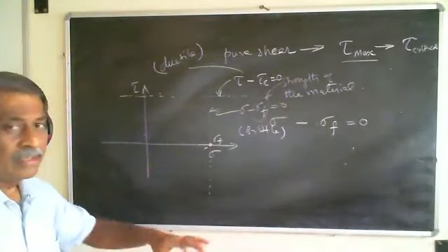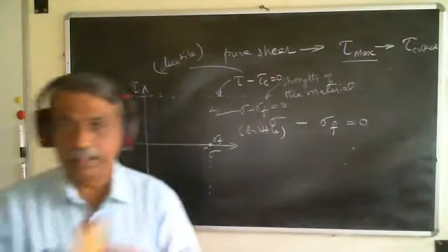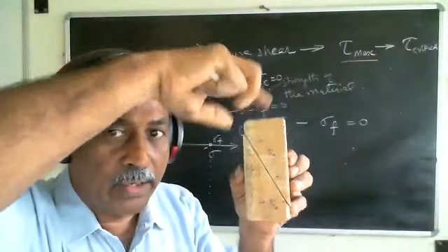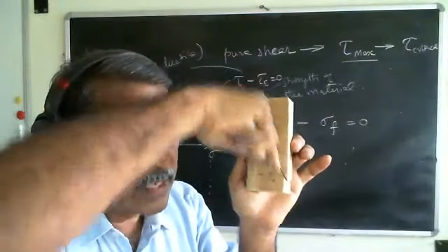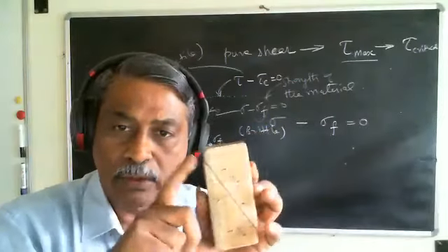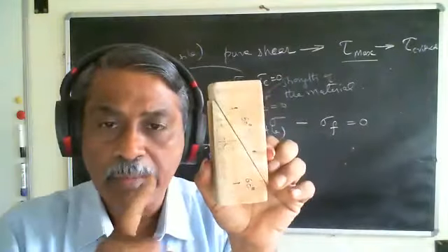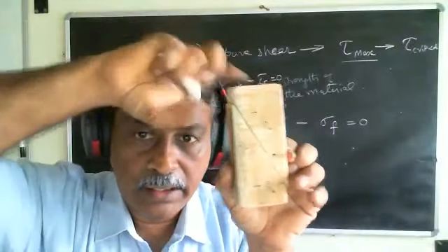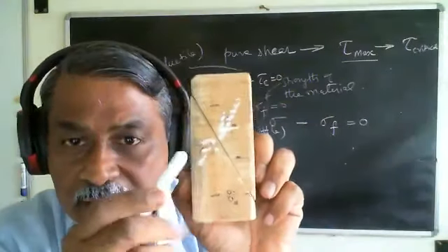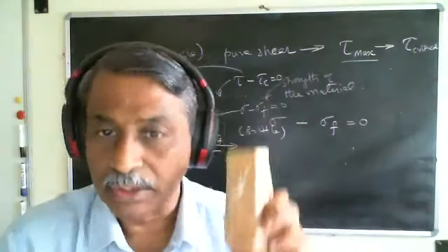Now, before going further into all those, let me also introduce something. We looked at this example, and there is a plane here, and when I apply a load over here, this is going to slide along the weak plane. And if there are numerous weak planes, then it is possible to define tau max, right? Now, in this, I made an assumption that the normal stress that is applied like this does not have any role to play in terms of the resistance to motion.